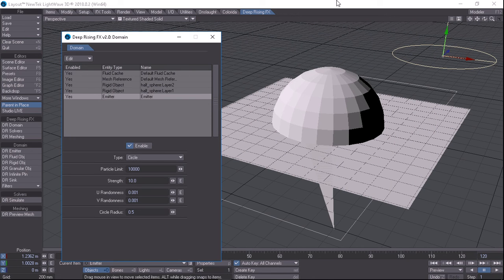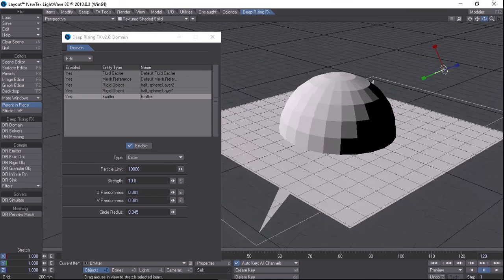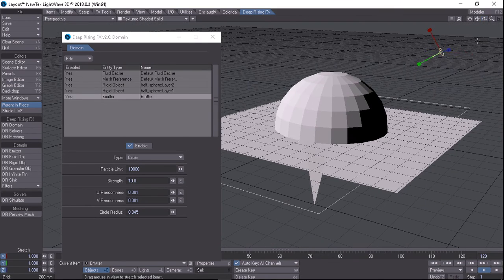Okay, so the particle emitter emits fluid particles, and just like the boundary particles, the default diameter is 2 centimeters and the width is 4 centimeters, and that is a constant throughout the simulation domain, so that will never change. What I'm going to do here is just put in 0 and press enter, and that will give me the smallest possible emitter, which will be 0.043. Then I'm just going to aim it at our obstacle. I'm just going to position it, and then I'll talk about the settings here.